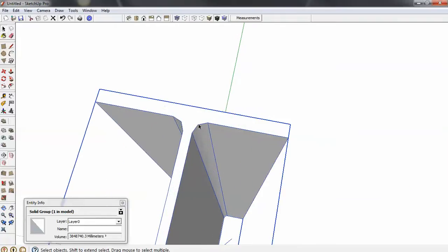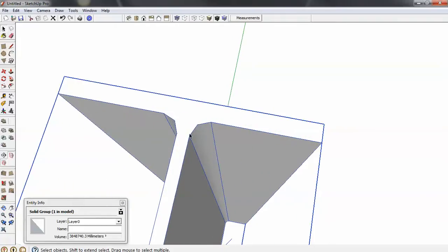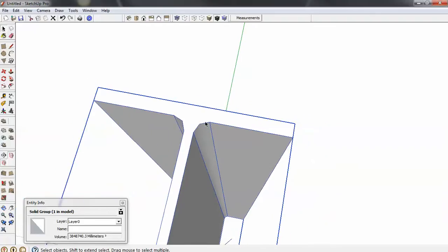Just remember that the only reason we draw the root radius in is so that we know where the flat bit finishes and the curve starts, in case we've got a plate bolted onto that. We don't ever want to foul with that. We don't need all the facets in here to know what's going on.